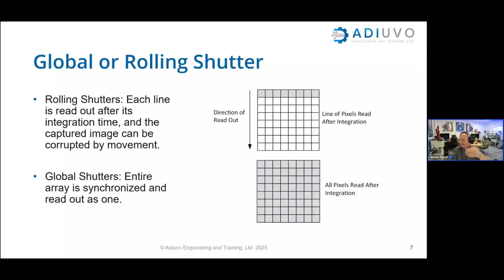And what that means is that it's possible to get in synchronization with events, and that's exactly what happens when helicopters appear to levitate and such like. It gets all synced up with the rolling shutter, and it's read out. And that can cause not only those synchronization events, but it can also cause corruption due to the movement, because there might be some movement or change between one line and the next.